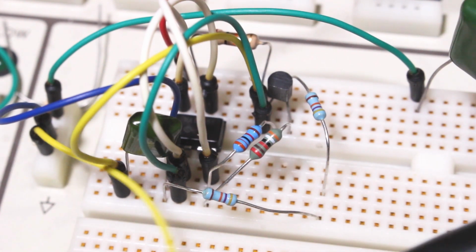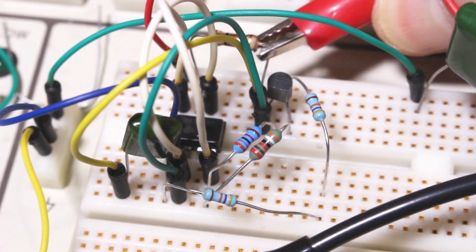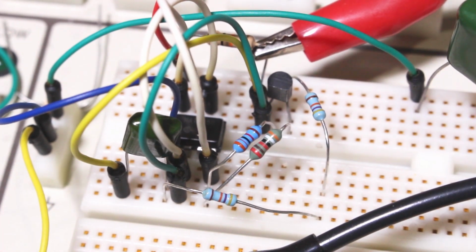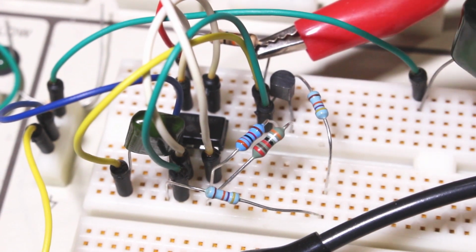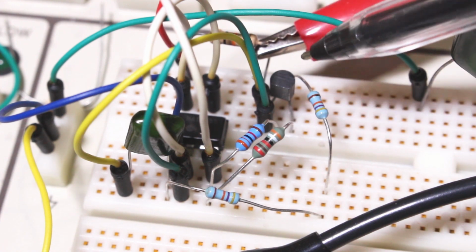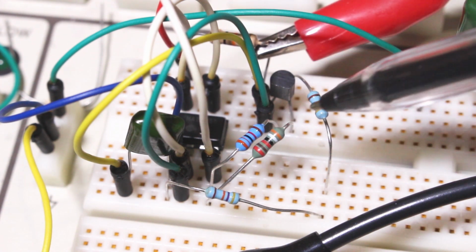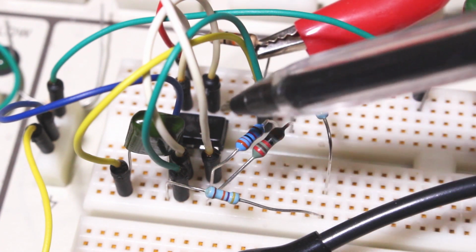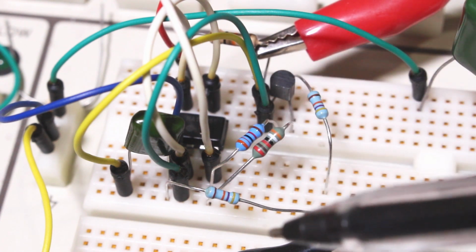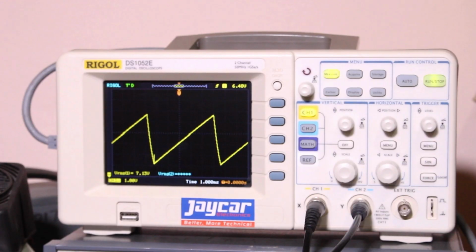Now, with all circuits like this, it's nice to do it in a simulator, but we should really build this up on the breadboard and test it. I've done that, and you can see now on the breadboard the 557 transistor. You can see the LM555 buried in the midst of the wires, and you can see the various resistors and capacitor there to make the circuit work.